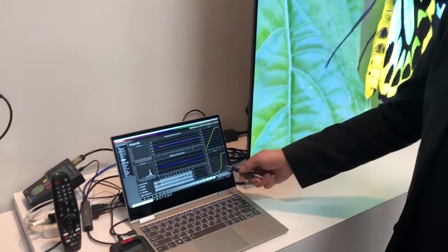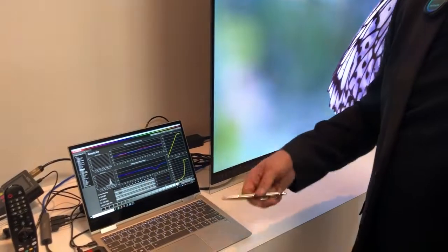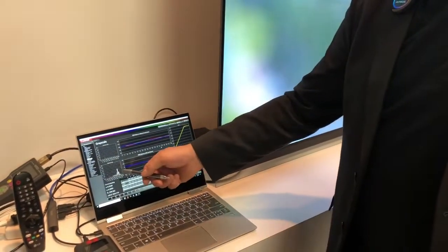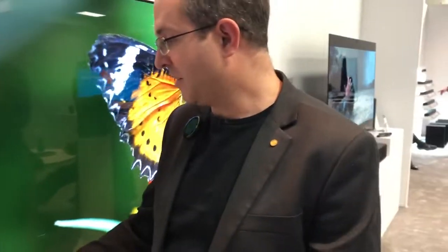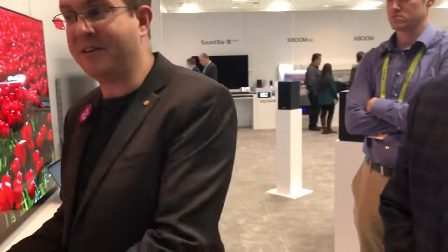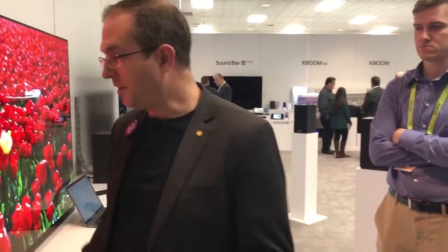So now we have delta E errors shown from the deviation from PQ, and if I had chosen a roll-off point that started lower down, which may look better, you'd end up with delta E errors across the board, but that would be unfair, because what you should be doing is checking what did you ask the TV to do, and now is it doing the right thing. So those are the 2 things that we're introducing here.